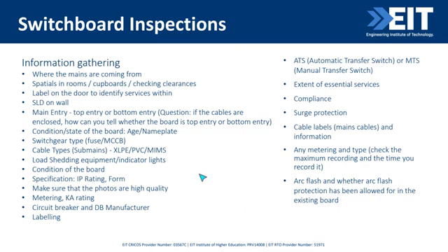So this slide, which will be in the slide deck, simply outlines what information you could gather from a visual inspection. So where is your mains cabling coming from? Above or below? How much clearance do you have existing in the room? Hopefully the board is labelled and can tell you some information. There might be a single line diagram that's available. Again, we look at that condition list we just went through, or look at the brand of circuit breaker types. Maybe you've got cable info or some IP rating that's identifiable.